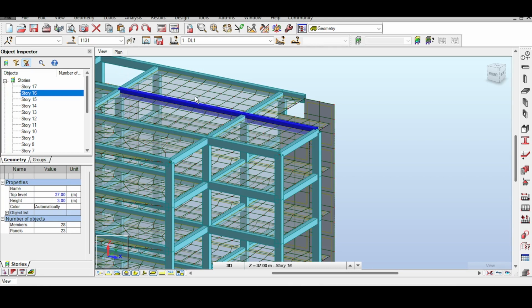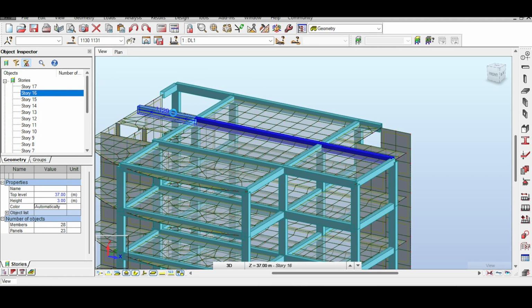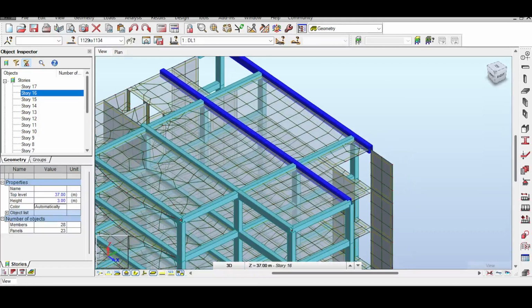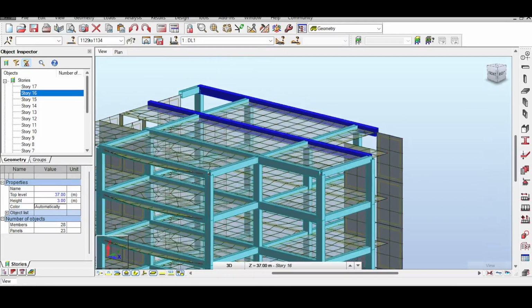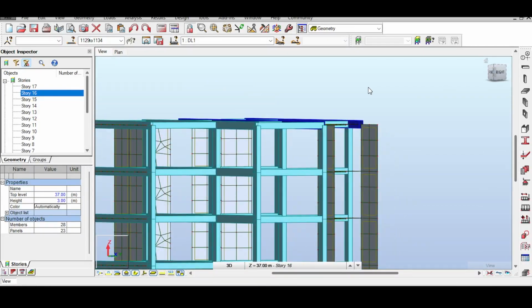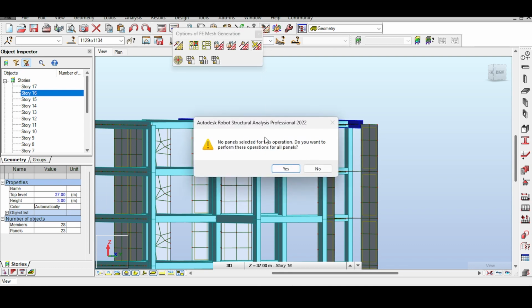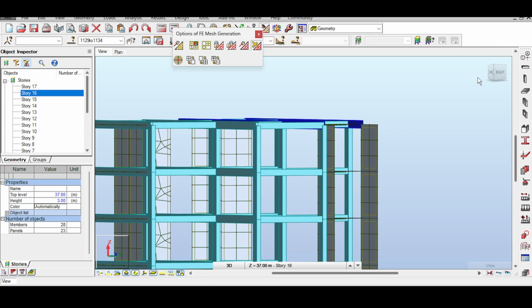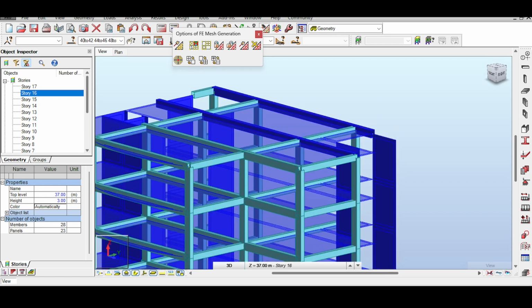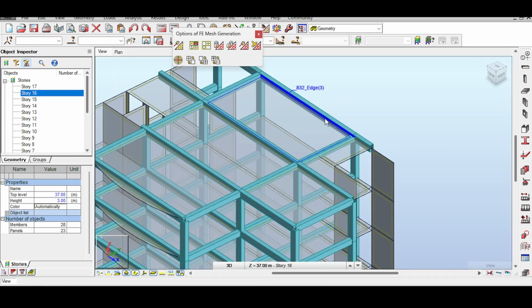Now I'm pretty sure I messed something up because I think previously I had some groups, and I'm pretty sure that I had some grouping based on slabs or something. So I have a big feeling that I messed something up in my groupings, but that's fine because I can still select using geometry. So that's still a silver lining, I guess. I'll unlock and go to mesh and delete the mesh so I have a better chance of selecting the nodes correctly. Of course, it's deleting the mesh. And for some reason, it selected everything, which is kind of cool. I have to select my beams again.